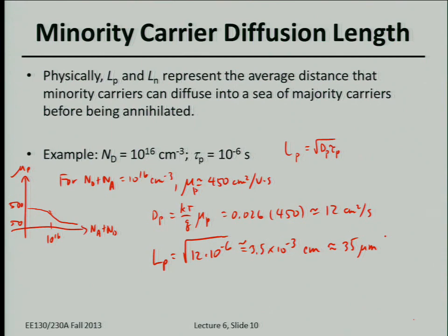In other words, what is the minimum length of this gate electrode? It's about 22. Actually, it's about 25 nanometers. Drawn proportionately, this is not bad. The source and drain regions have to be shallower than the gate length for this transistor to work properly. So typically, the depth of these heavily doped regions in the surface of a silicon wafer is going to be less than about 10 nanometers.